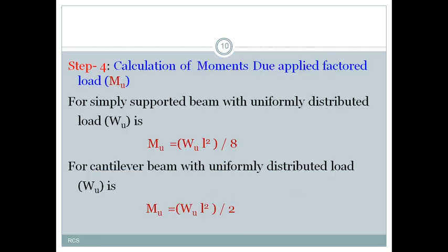Right. Next, now we have to calculate the moment due to the applied factored loads. So you will be given the factored load, or sometimes directly the factored bending moment, based on the given problem. But actually we have to calculate first the dead load and live load, and based on that we have to calculate the design loads. From the design loads we have to calculate the design moments, or factored moments.